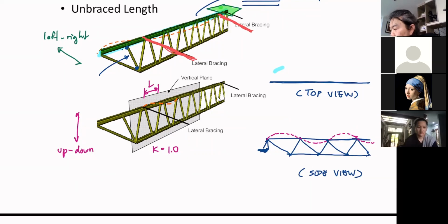So we will have any, say, bracing coming in. Any brace point will be the point that will help prevent the lateral movement of your top chord in that plane. If we have that, your top chord, because that's a support, right? It may buckle like this.